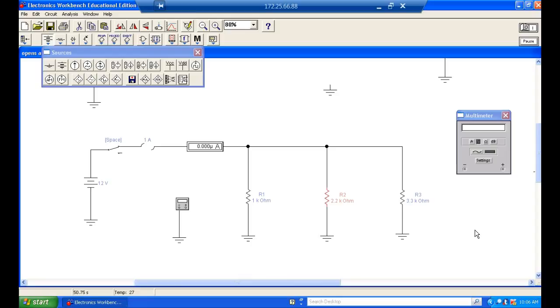The current flow goes to 0. So how much work are we getting? None. No power, no heat. So this is why your circuit breakers and your fuses are connected in series. In a series device, when it opens, you create an open circuit. In a parallel circuit, if you create an open, it's not an open circuit.